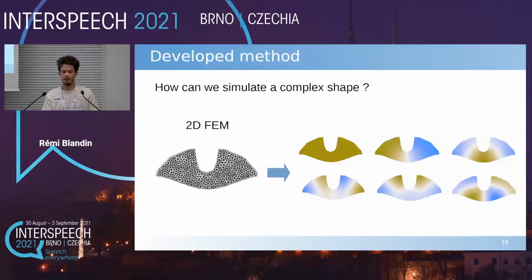So at this point, you may think that we use again finite elements and it will decrease a lot efficiency, but in fact, it's not the case, because here it's a two-dimensional problem, and the number of degrees of freedom is much less than in 3 dimensions. And as a matter of fact, computing the transverse modes for about 100 segments will take only a few minutes using a regular laptop with one processor.